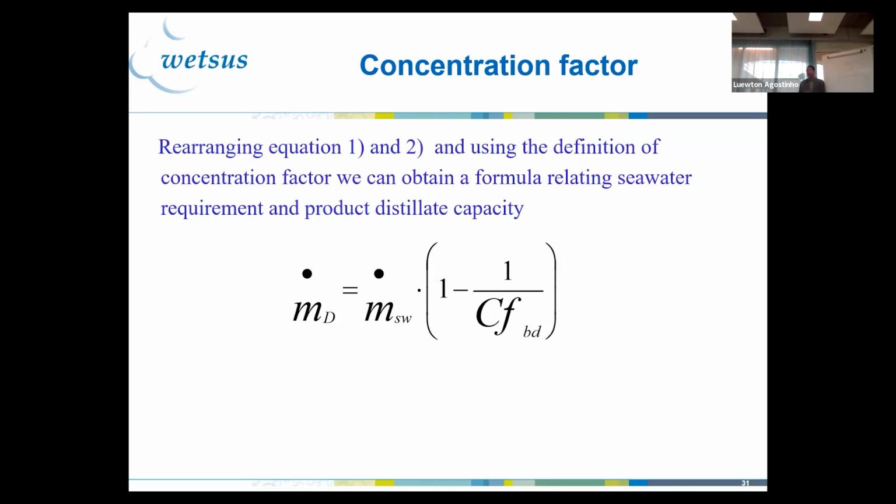More or less. So if you use 100 liters per day and you have 10 to the power of 5 people, to desalinate water for the city of Leeuwarden you have to produce an MD of 10 to the power of 7 liters per day. So your plant has to produce 10 to the power of 7 liters per day, on average, of course. That's a very simple calculation, but when you start your calculation, that's the first number that you should get.